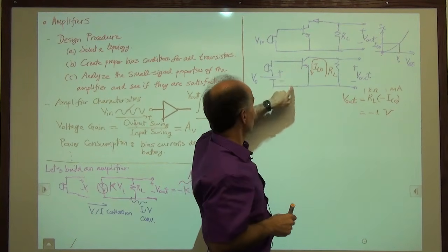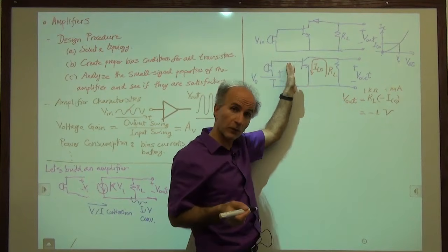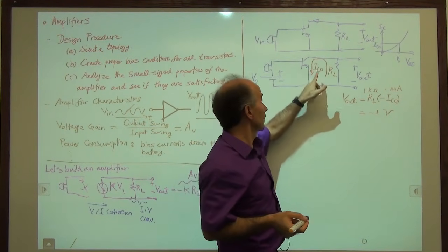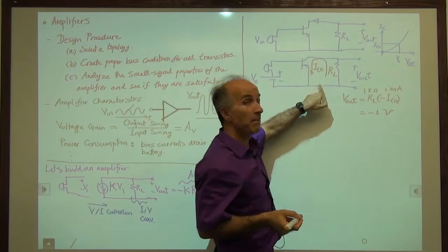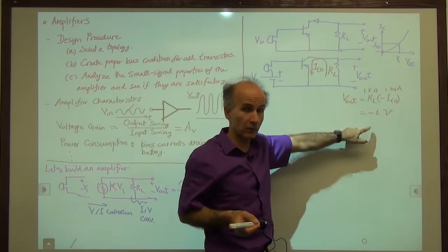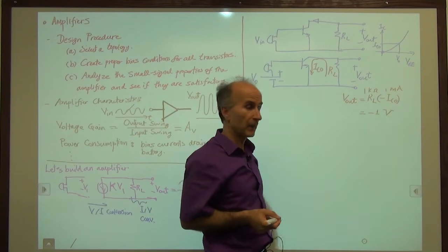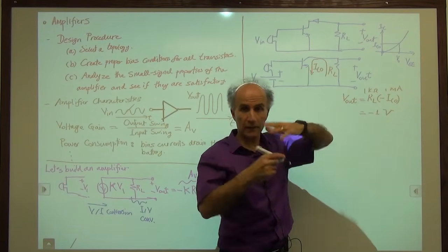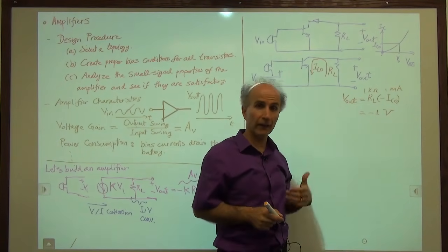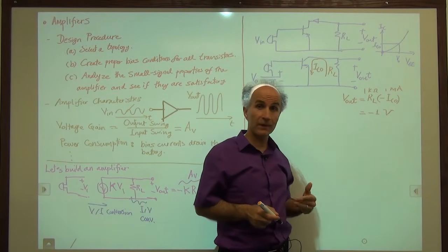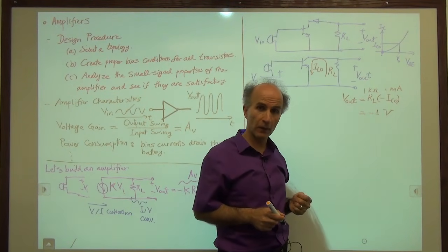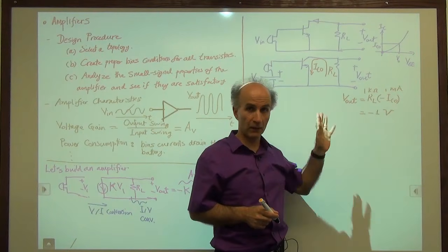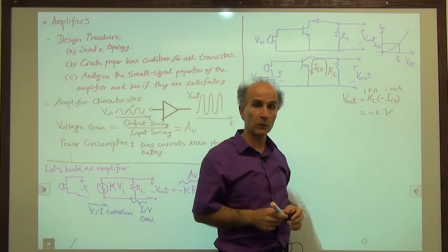If the base voltage is, say, 800 millivolts with respect to emitter, then the collector has to be at least 800 above the emitter, certainly not below the emitter. So that means that this condition cannot hold, this current cannot flow, the device is dead. In fact, if you are curious, the device enters saturation, as we discussed before, but the point here is that this topology is not what we want.